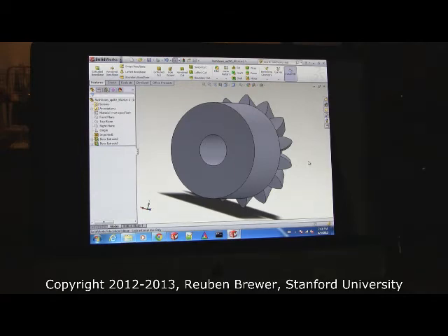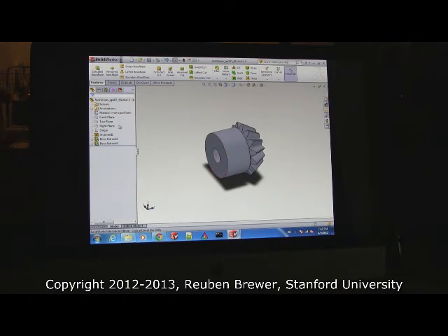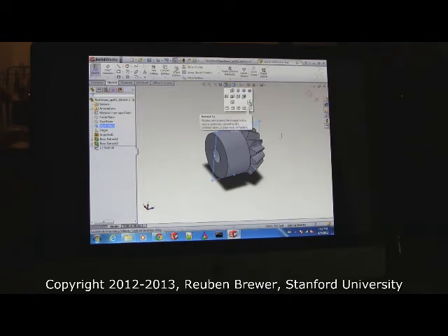All right, we're going to steam ahead until we get through it. Okay, this is the critical part. You guys really want to get this. This is the first time we've ever done a cut. Okay, we're going to do a non-standard cut. Everybody select right plane. Now up here, see on my screen, Extruded Cut. Press that. Now change the view so it's normal.